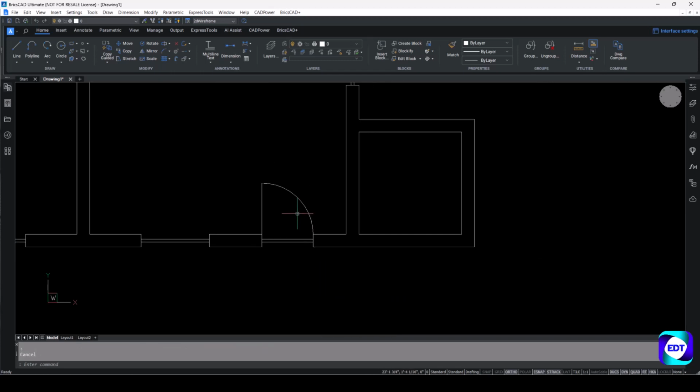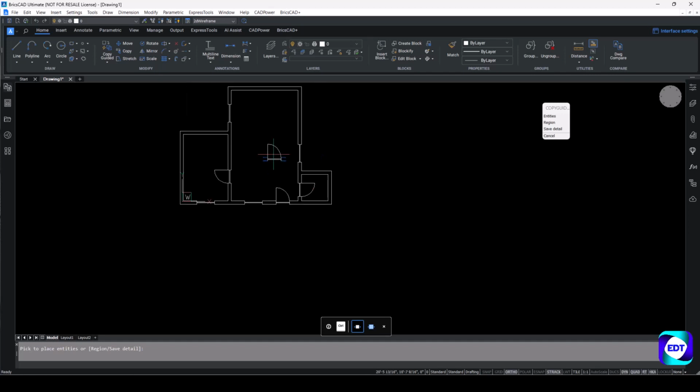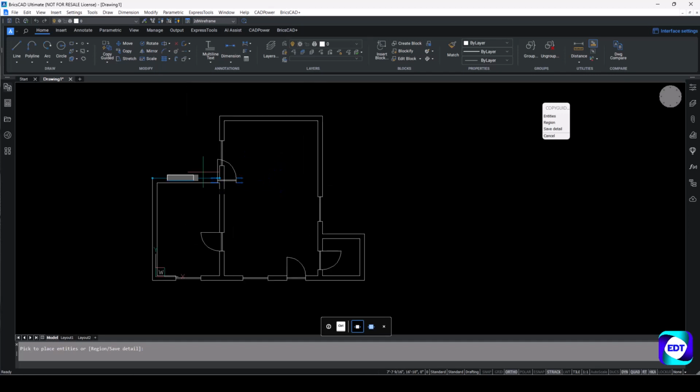Now you want to use the same symbol for other locations. The problem is when we are using a copy guided, again you need to trim the lines, and this is a long process. So we can use the copy guided and the move guided. Software will automatically identify the path, and the best thing is you can change the orientation easily and put a value, and software will automatically do the trimming for you. So you don't need to do it manually. By using those methods or those positions, you can easily place this door, so you don't need to do things manually one by one.